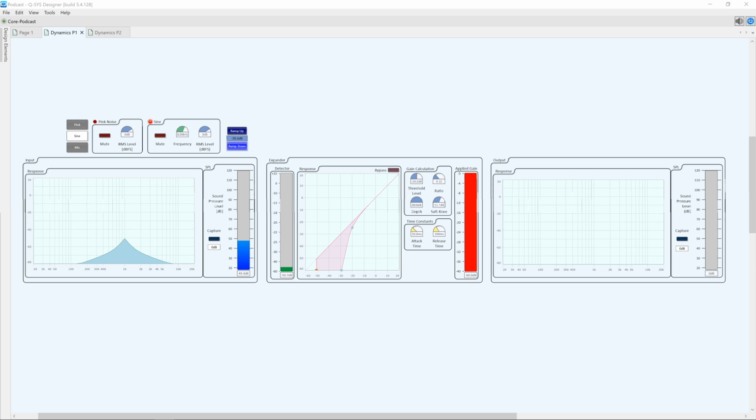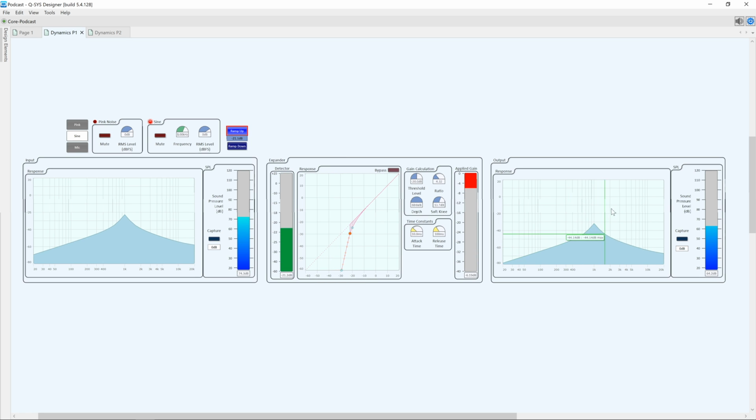Our next one is an expander. An expander is a fancy gate. All it does is, as we hit a threshold, our gain ratio slowly reduces the amount of negative gain applied until it opens up. So this is nice. As our signal increases, it makes a smoother increase in audio signal to increase our dynamic range, where a compressor and limiter were used to reduce our dynamic range. Expanders and gates are used to increase dynamic range between our loudest and quietest signal.